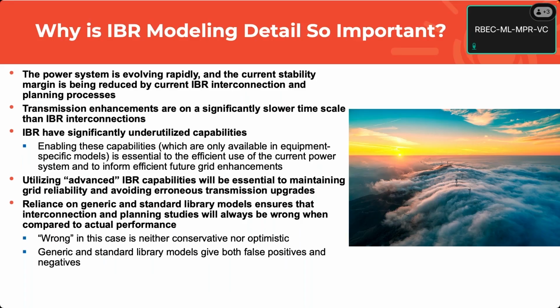The other thing we talked about, in addition to the common tools, the PFRs, the AVRs: if we're not modeling in detail, we're never using the new, fun, cool features that manufacturers are coming up with and innovating with all of the time. We're stuck with only the things that are in the generic models, which is regular primary frequency response with a regular droop, voltage control with no hysteresis or anything like that, one gain, one ramp rate. So a lot of capabilities are left off the table, and any custom solutions you can't use, because you can't represent them in those types of generic models.